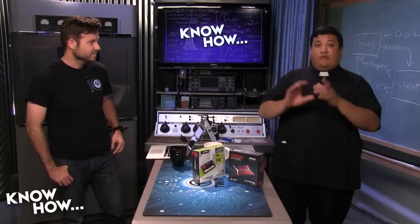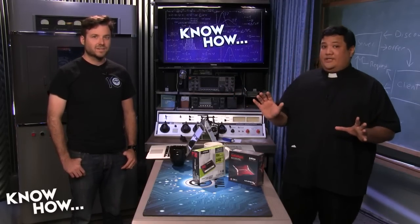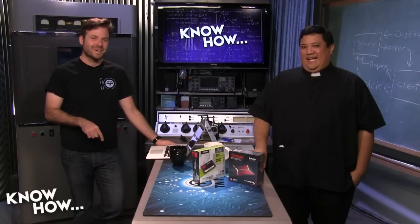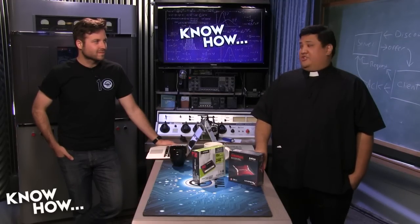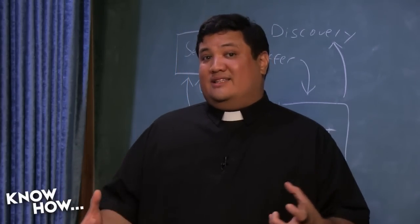Okay, first of all, very good on noticing that your hard drive has gotten loud. That's actually a really good sign. You're going to want to back up right now. If you're using that computer to watch this right now, you should probably be backing that up. If it's getting loud, it means the bearing is starting to go. And if the bearing starts to go, you're going to get track misalignments, the motor's going to heat up, and eventually that thing will just shut down. I've had a hard drive that started clicking, and I could feel my heart sink. Exactly. You don't want to get to that point. And the nice thing is the prices of hard drives have really, really come down.